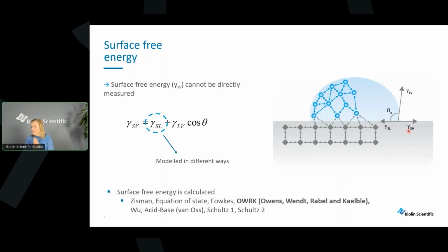Now, how do we then measure the surface-free energy? The answer is actually we don't really measure it, we have to calculate it. In this three-phase contact point where we have the solid, liquid and gas in contact, we have different forces affecting this contact point.